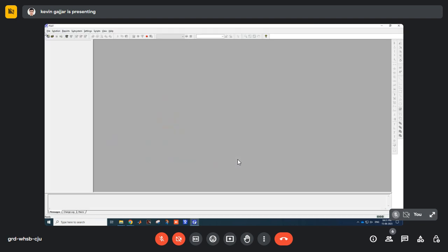This is the first window of the module PSET. As we saw last time in the PSSE software, to save the solved load flow we use the data format called .raw, and the same file we can simply use here. We just have to use import, select which version the raw file is in appropriately, and then select that raw file.